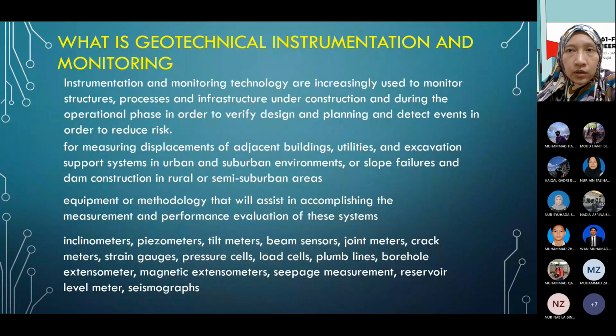In order to prevent the differential settlement in future, they did some mitigation work by placing some joint bar, if I'm not mistaken. So during the installation, they needed to install some sort of instrumentation tool. It gives some idea of whether you are reaching the required depth or length specified in the design. That's the reason why we need to use instrumentation and monitoring during pre or post construction.